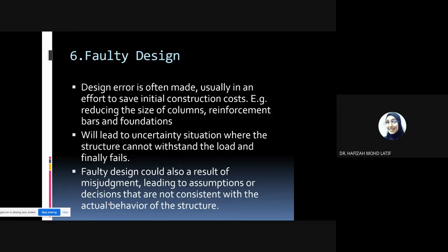Okay, do you know the suspended slab? It's not on the ground, yeah? It's on the first floor. So the floor slab of the first floor, underneath, means the ceiling of the ground floor. If you look up, it's like your ceiling. So it's a concrete ceiling. They don't have a plastered ceiling to cover the slab, so we can actually see the slab. There was a lot of water underneath. It was so damp, not only damp, but you can see droplets of water on the slab. Like you can actually collect it. The condensation is really, really bad.